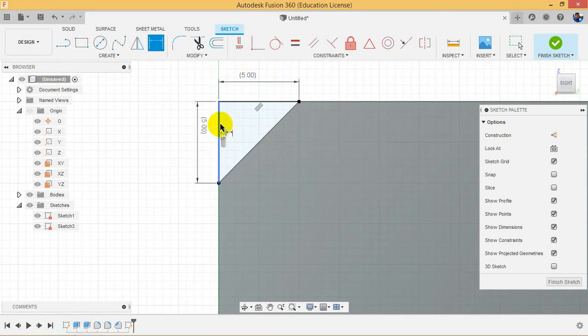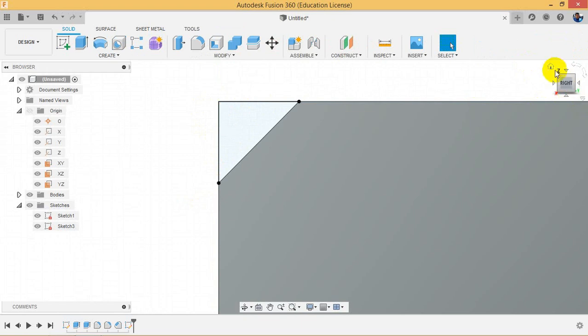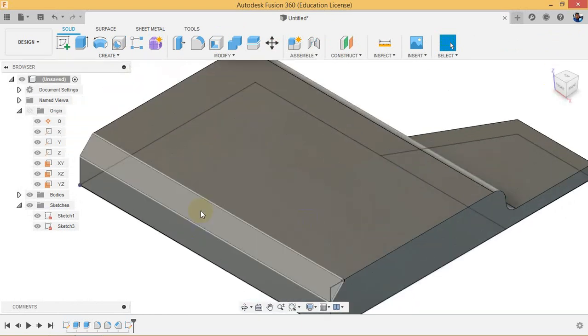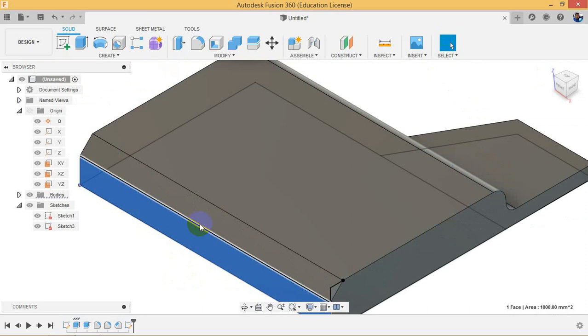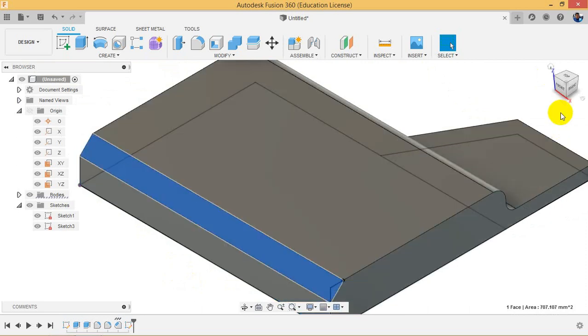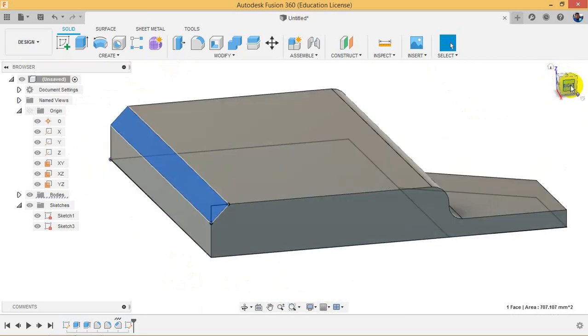So the chamfer is created like going to cut this portion like 5 and also cut this portion in 5, and then join them with a line and create this face, and this face is not tangent with these faces, they are just connected. So that's how you can create the chamfer.